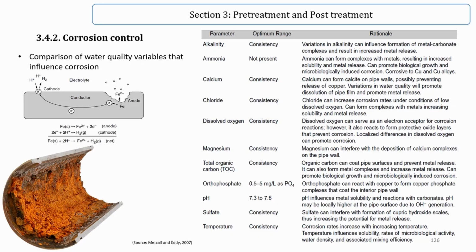In addition to chemical water quality, microorganisms in reclaimed water may directly or indirectly impact corrosion through the development of biofilms on wetted surfaces of pipelines, condensers, and process tanks. Microbial activity within biofilms produces acid-forming gases such as carbon dioxide and hydrogen sulfide that can lead to localized corrosion.